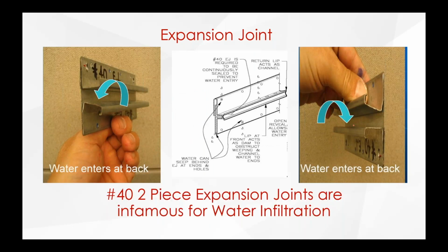I took this from a consultant that had written this years ago. What they were saying is, if you're going to use a number 40, we're going to recommend sealant right here. I'm not a real big fan of sealant because it requires maintenance. The other thing that I don't like about this is you've got perforations, and anytime you have a perforation, if water gets exposed to it, water could get inside of it. We don't want that. You notice no matter which direction I put this number 40 in, I've always got this little area that could fill up with water right down in here. And I want to avoid that.